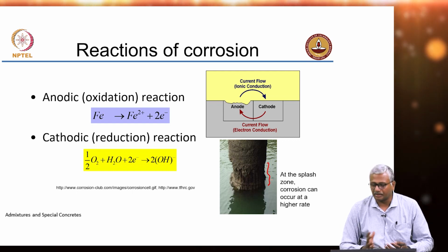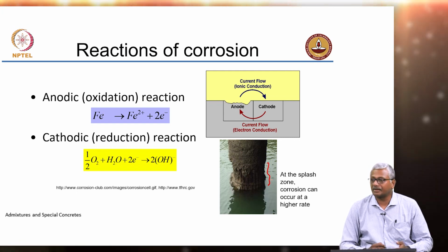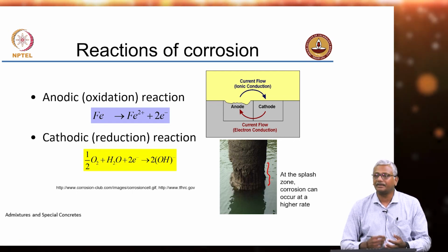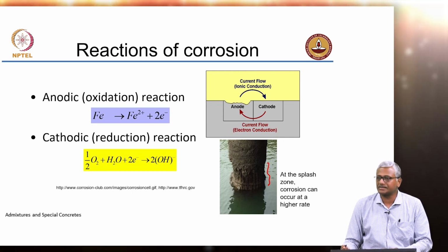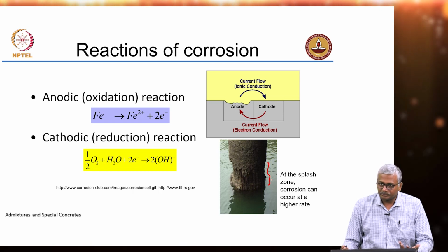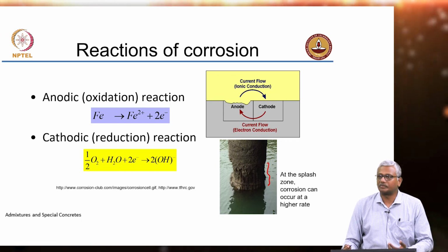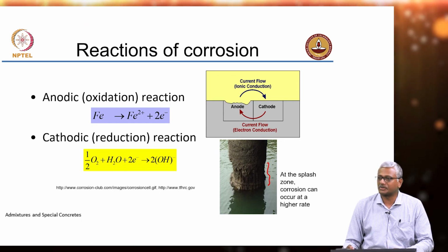Okay. So, there are several mechanisms that lead to deterioration of the concrete, but primarily we are interested in what causes the corrosion of the reinforcing steel, and in seawater the agent that leads to corrosion obviously is, what is there in seawater which causes corrosion? What salt? Be more direct. Chloride. Yeah, there is chloride in seawater which causes corrosion.